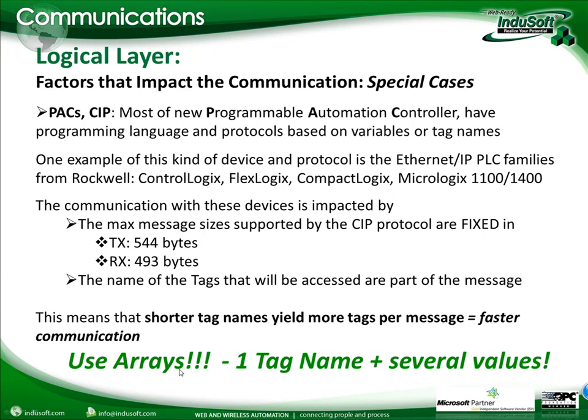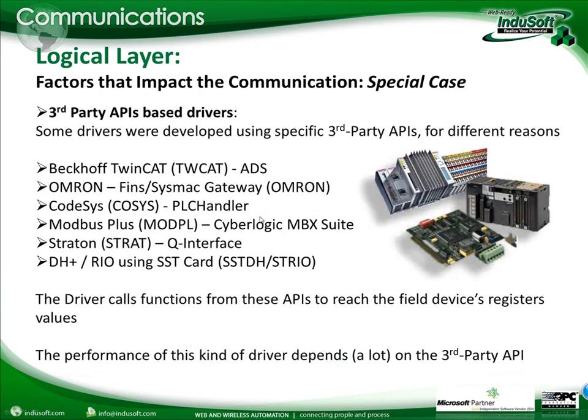Use arrays. Okay? And finally, we get the drivers that use specific APIs from the manufacturers. That's the case, for example, for Beckhoff TwinCAT. We don't talk to any Beckhoff PLC specifically. The ADS, which is the library provided by Beckhoff, is the one that talks to their PLCs.